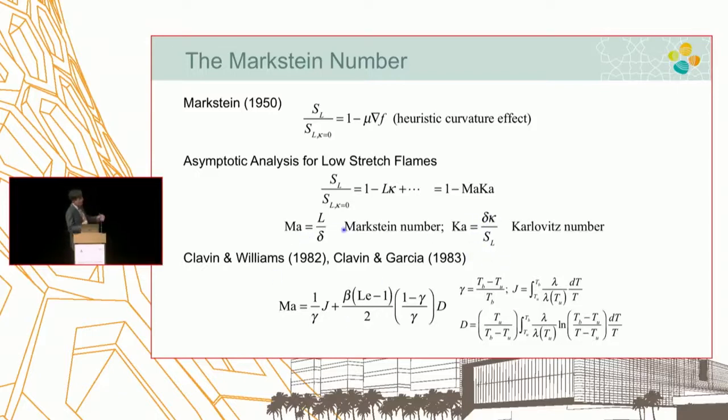And those are the two important fluid dynamic parameters combined with the mixture property that determines whether the flame will accelerate or destabilize depending on the system. And there's a further asymptotic analysis that actually derives the expression of the Markstein number in terms of a Lewis number as well as a heat release parameter. So those are a brief 10-minute review of the combustion theory. These are some of the major accomplishments done by asymptotic theory when supercomputers were not around.